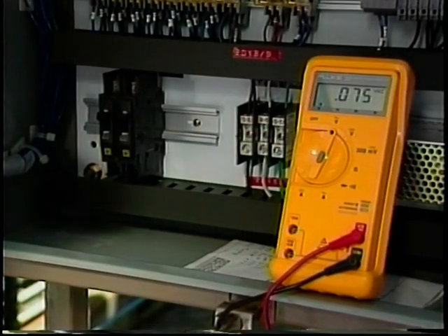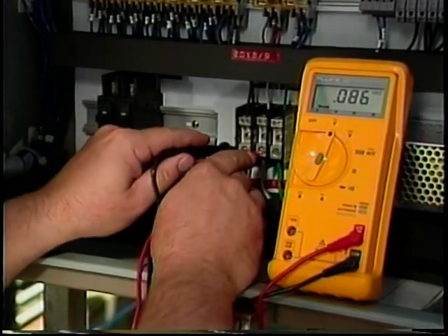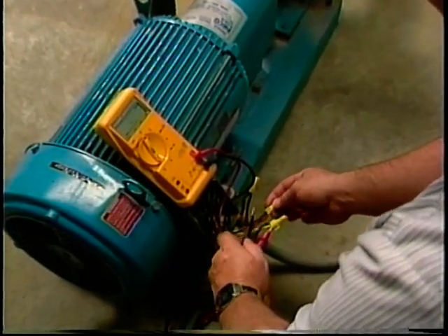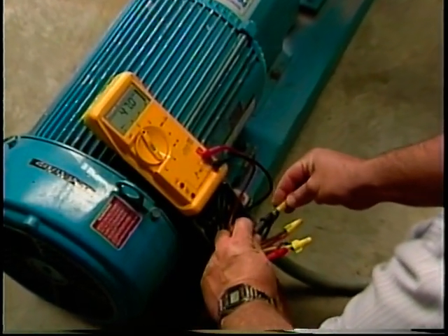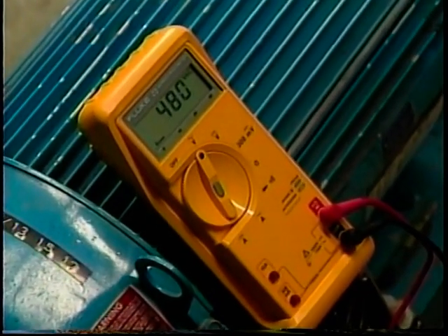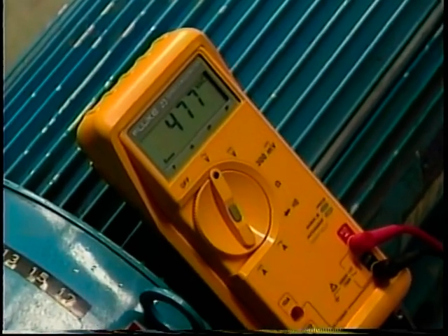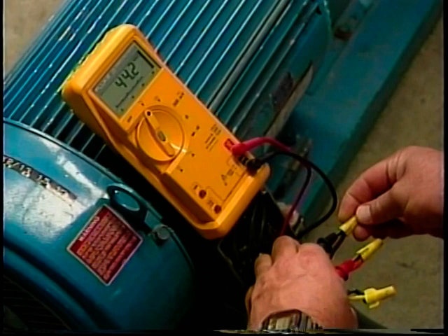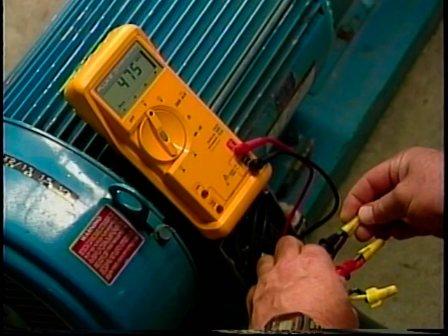Ghost voltages enter a meter through test leads not connected to a circuit. The test leads act as antennas for stray voltages. To ensure true circuit voltage readings, connect the DMM long enough until a constant reading is displayed and turn off nearby sources of power that may cause ghost voltages.